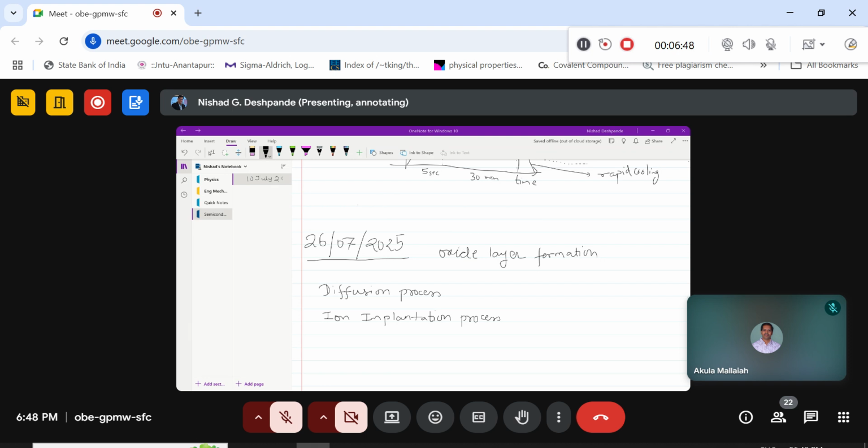So particularly one can have a very fast ramp at the initial time, and then a very good saturated portion where a controlled or uniform oxidation growth can take place. Slowly one can either ramp the process downwards in time with respect to the temperature, or allow the system to cool naturally. So there are different parts that can be controlled through this RTO process.